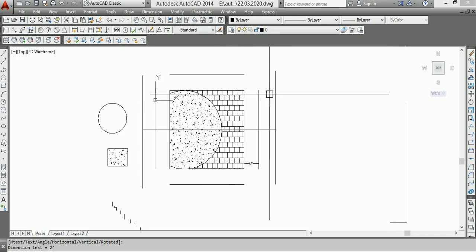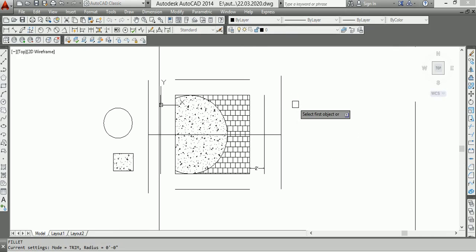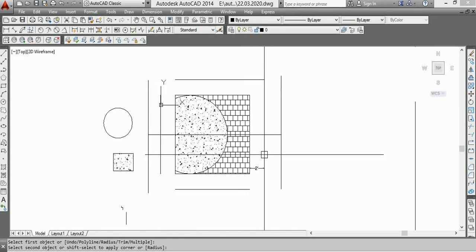And then now I want to close the line. Closing the line is actually F space, it is fillet. You can select two line. Again, to go to the last command, we can just press space without giving F space, because within this time we have not given any other command after fillet.